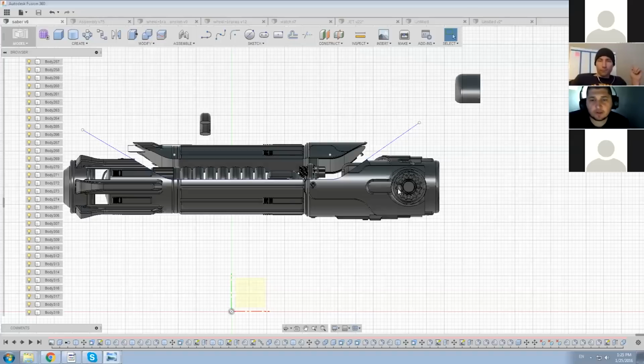You don't really retopologize this mesh, you create a low poly version of it, and then you bake all the details onto it. You can bake the details right off of this onto any low-res cage.